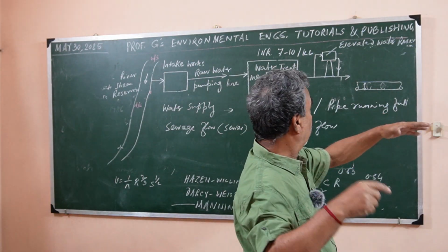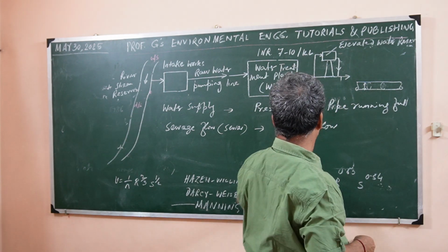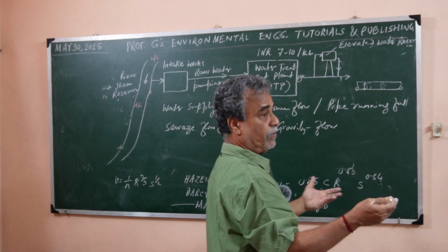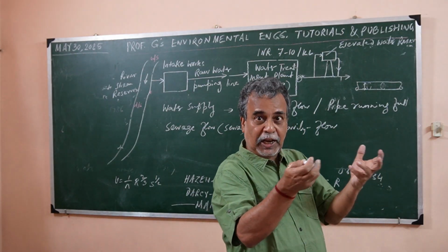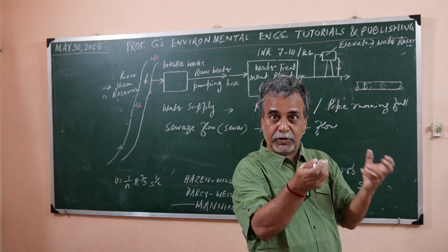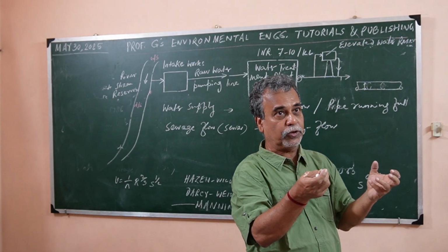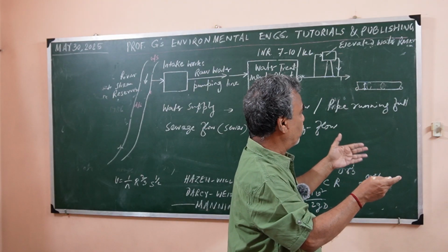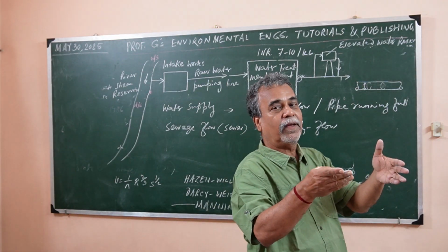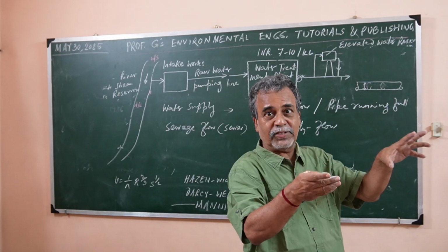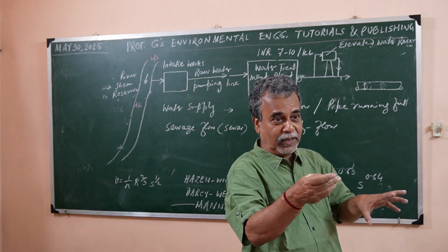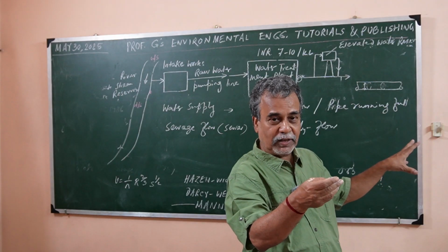But in the sewerage system, remember, it is collection. That means it is just the reverse. It is collecting the domestic sewage from different buildings, then going to the submains through laterals, then the mains, then the intercepting sewer, that we already have explained.